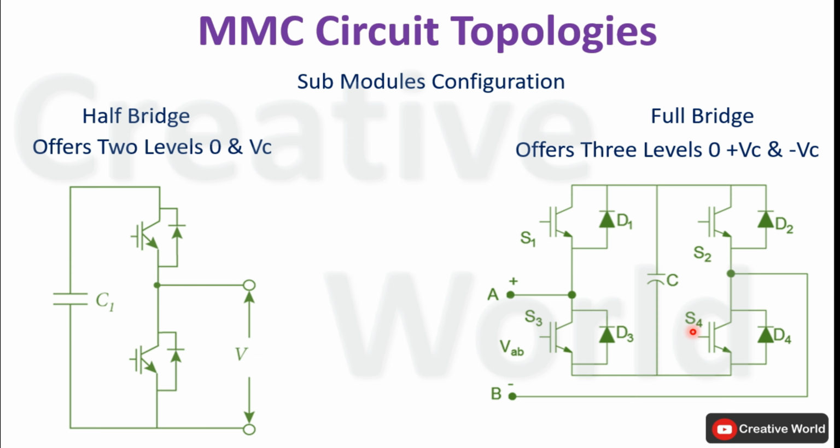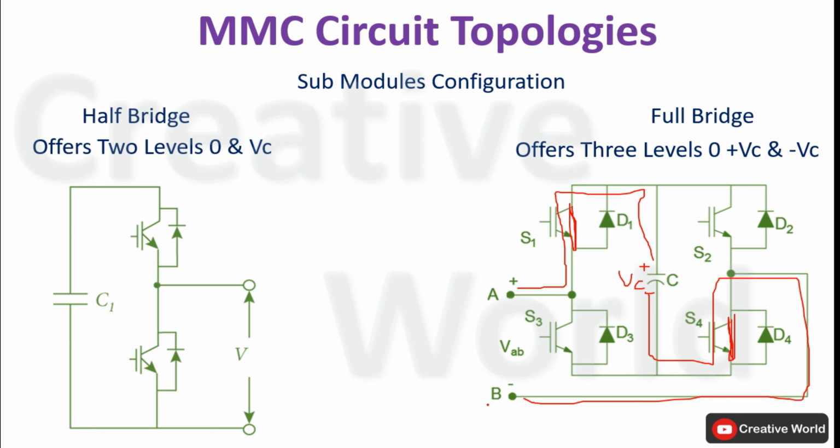And one more thing to keep in mind is that at a time only two switches are active while the remaining two are inactive. Now I am assuming S1 is active, it means S1 is short circuited and S4 should also be short circuited. These two switches are opened. So how will the output voltage be retrieved? Here positive VC is appearing. So using this path, positive VC is appearing across this point A and negative VC is appearing through this path on point B. In this case we are getting positive VC. So this is the first voltage level retrieved from this full-bridge configuration.